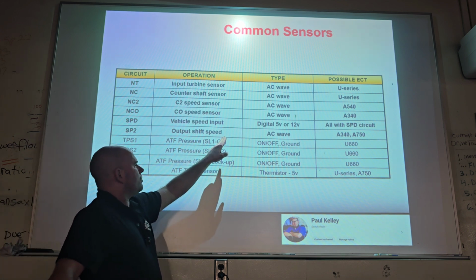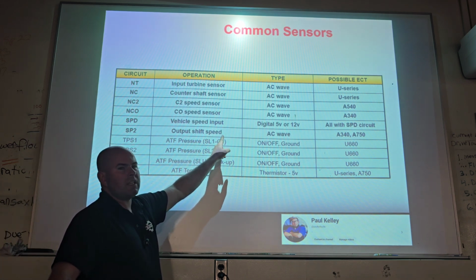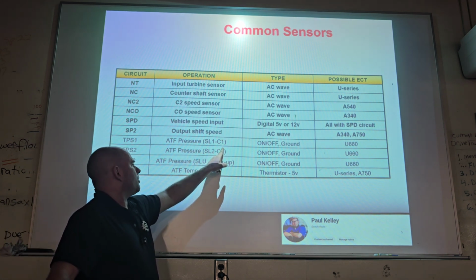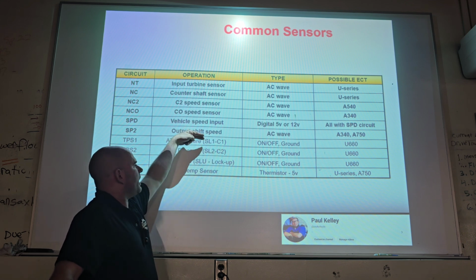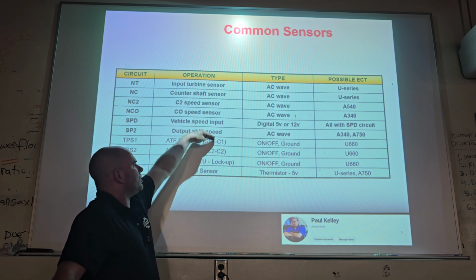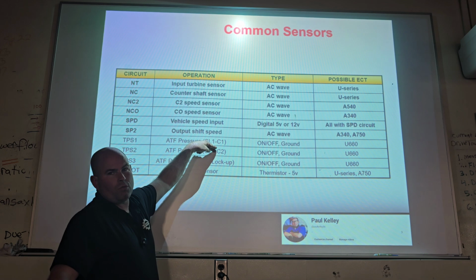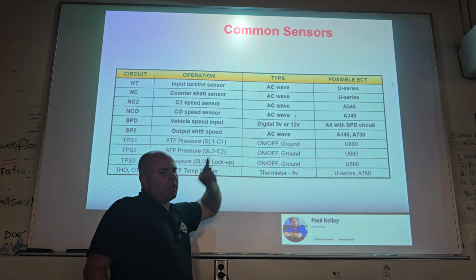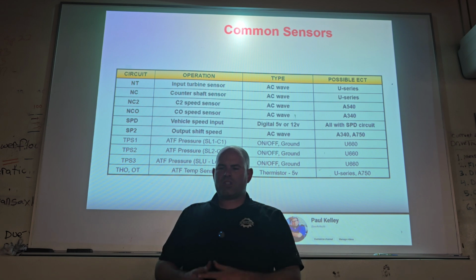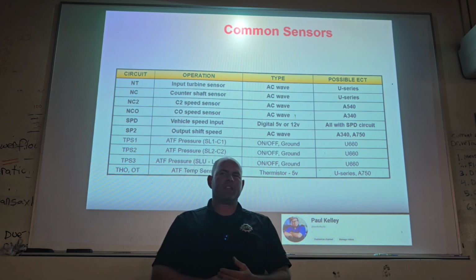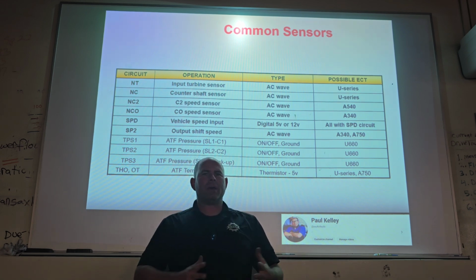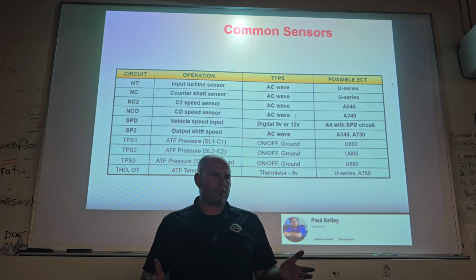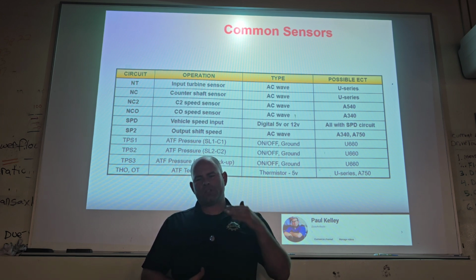That would actually give you the C1 pressure and the C2 pressure, which are controlled by shift solenoid linear 1 and shift solenoid linear 2. All right, so to me, this is the ideal, because if you have a shift solenoid and the circuit's good, the ECM has no way to know if it's working or not, realistically. So they've done a little step further.